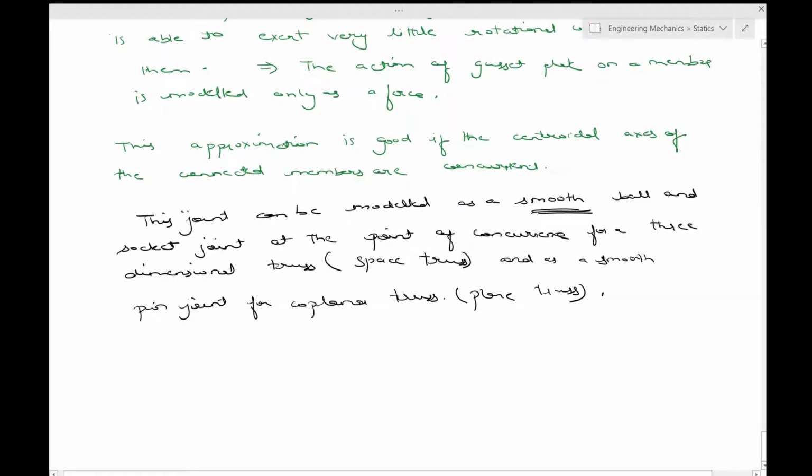If you have to take up the weight of a member, then you assign say half the weight of each member to the joints connected to it, and the member itself should be treated as weightless.